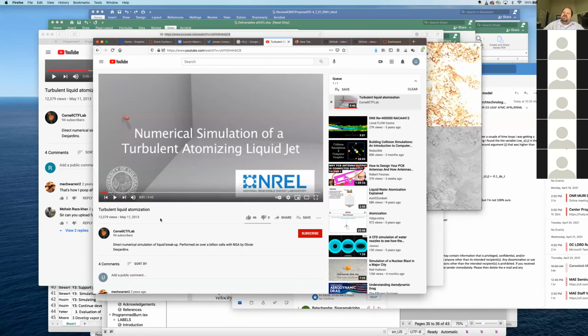So this is a movie from Olivier Desjardins. For low speed flows, he's a famous multiphase atomization guy at Cornell. This is a simulation of a diesel-like jet being injected at diesel-like conditions. This is a direct numerical simulation, meaning there's no subgrid modeling and no turbulence modeling. They are solving the volume of fluid equations for a gas-liquid flow.